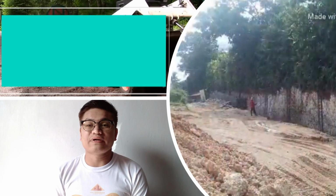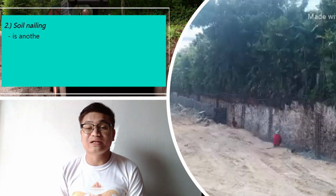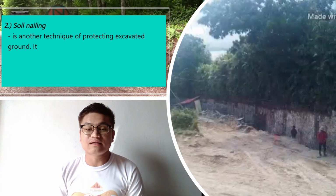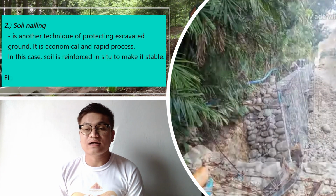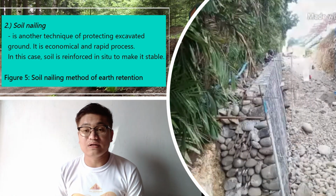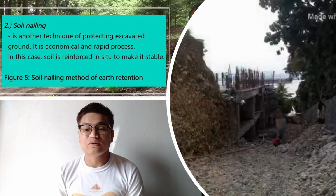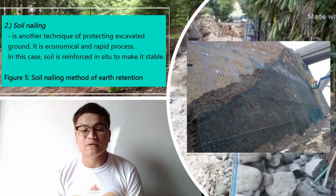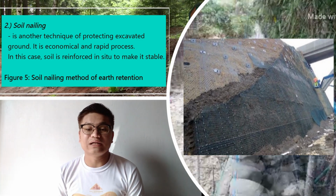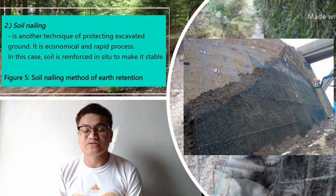The second type of excavation support is soil nailing. It is another technique of protecting excavated ground. It is an economical and rapid process. In this case, soil is reinforced in situ to make it stable. Look at the screen: figure 5, soil nailing method of earth retention.